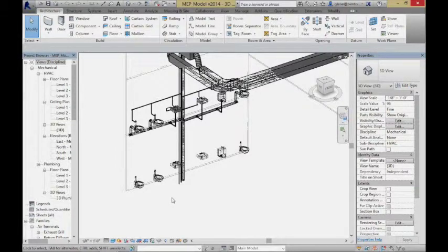We can keep these all together in a single model file, or we can link some models together. We're going to learn about this whole notion of linking together model files where when people work from different disciplines, if they don't actually want to physically share a single file, I can take your model file and link things into it. Use your model as the basis, but then add my elements in it, and we can control those things individually. And that's a very useful way of doing things.